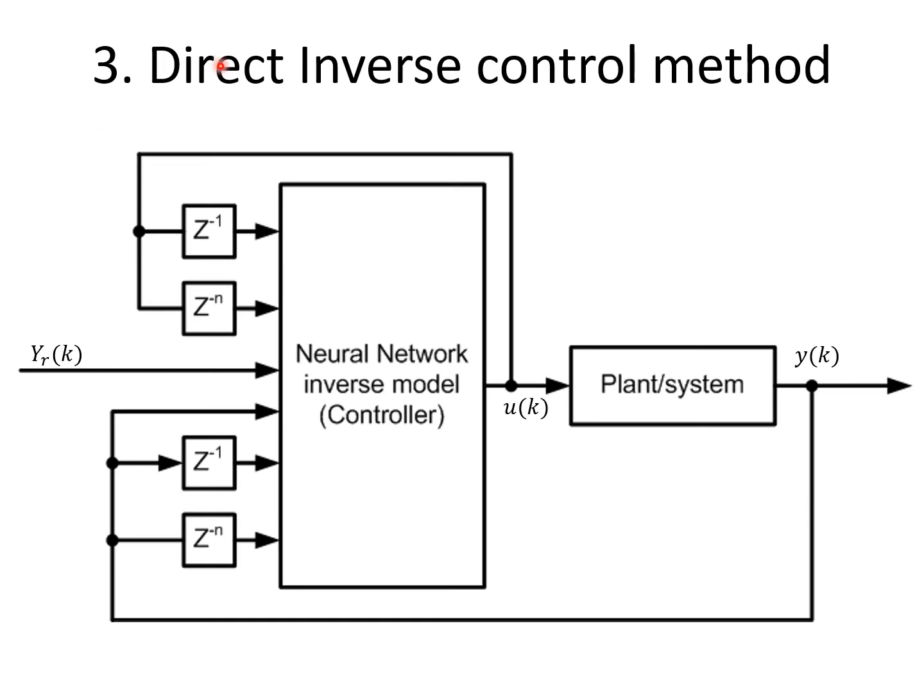And this is when you use it directly. We call it the direct inverse control method, because the one that you trained just now using your general method, the open loop method, or if you use the closed loop specialized method, you have trained it before with the same inputs and outputs. Put it inside as the controller, and it will be sending out the manipulated variable to control the plant system, using whatever set point that you want. You have trained it on the set point, and you implement it straight away like this.